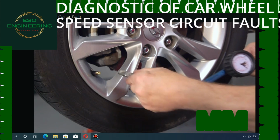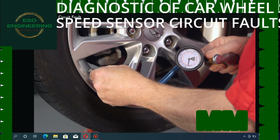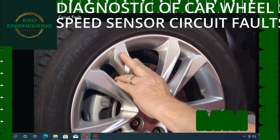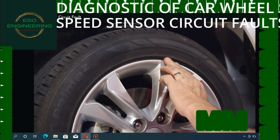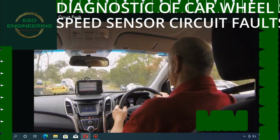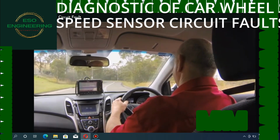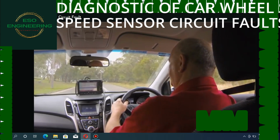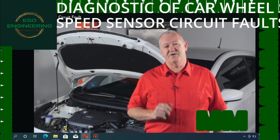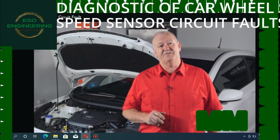Inspect all the tyres for correct air pressure and the correct size. If they are not all the same pressure, adjust the pressures to specifications. If not all the same size, replace the incorrect tyre. If any of these faults were found, then clear the codes, road test the vehicle, and verify that the DTC doesn't reset. If the tyres and pressures are all right, or the code returns, then you'll have to perform the following diagnosis.